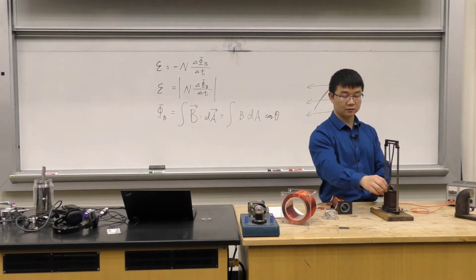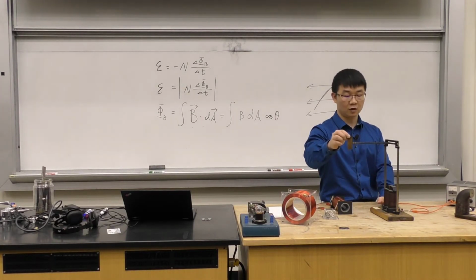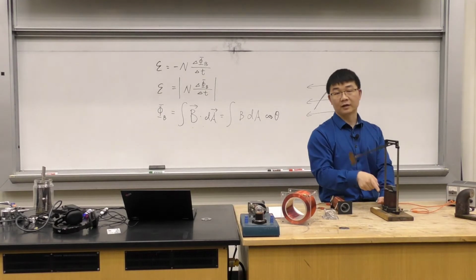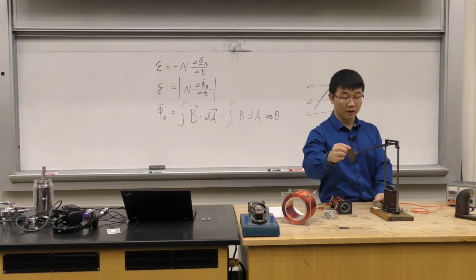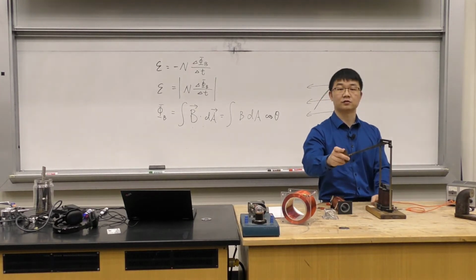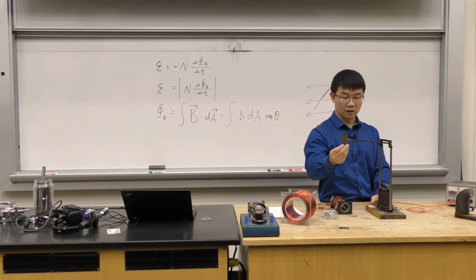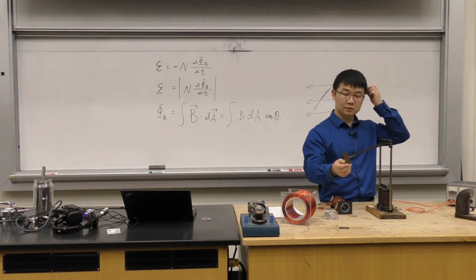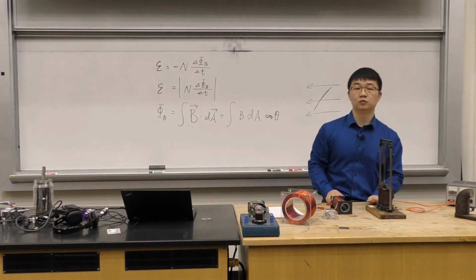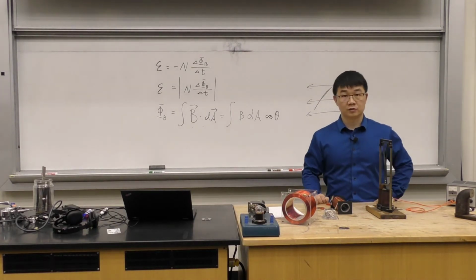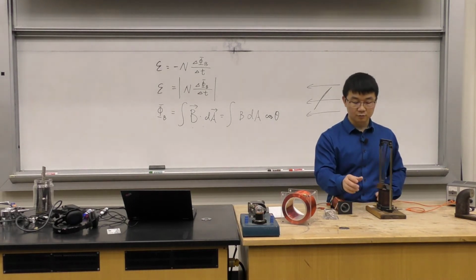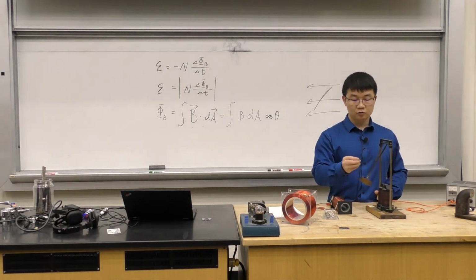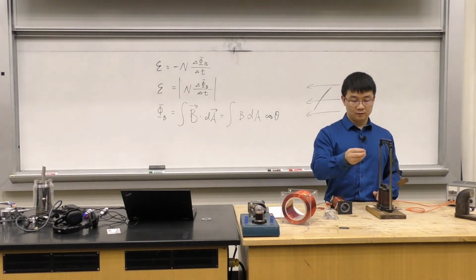Once they become magnets, you will have a piece of copper moving in a magnetic field. So there will be some eddy currents here, induced current. Again, eddy current is just another name for this induced current on a big piece of conductor. And the eddy currents, the induced currents, they always want to fight the change, right? What is the cause of the change? The cause of the change is the motion, right?